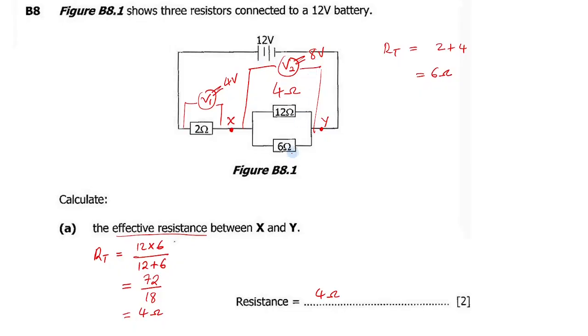So now that we know it, the question is asking us to find the current here, because when 2 amps comes here, it is the one coming out of this side, and also coming out this side, going that way. Now when it comes here, some is going this way, some is going that way. So how will we know that going there? We would need to use the voltage we have found at this point, which is 8, with the resistor here.